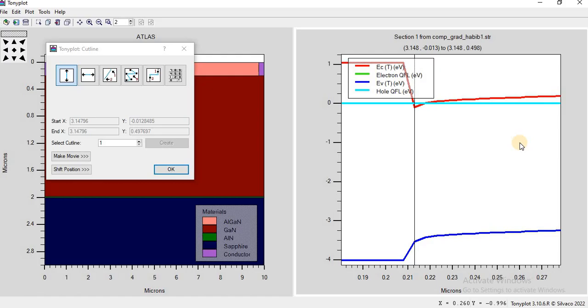That's why we call it high electron mobility transistors. HEMTs make use of high mobility electrons generated using this heterojunction over here, or in the device structure it's over here. In HEMTs, the electric current flows between a drain and a source element via the two-dimensional electron gas, which is located at the interface between the two layers of different band gaps, and that's why we call it the heterojunction.